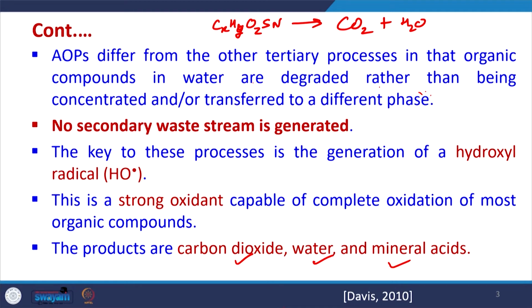Similarly, in other techniques like coagulation and flocculation, it goes into the sludge. Here there is no phase change, we are not moving the pollutant from one phase to a different phase. Here we are degrading the pollutant itself. So, this is the target in the AOP.